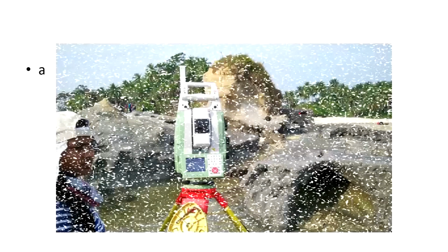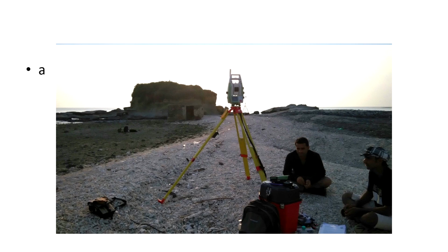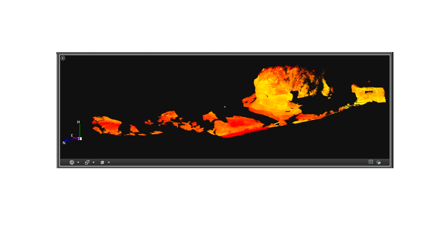So I will show the example of the trench which we did with the total station here, and this is the total station which we used. It has an inbuilt scanner also, what we call a terrestrial scanner, and this helped us in preparing the overall topography of the exposed trenches. Okay. And because we took this from different angles, for example, one measurement was done from here, another one was done from here, and these were merged actually.